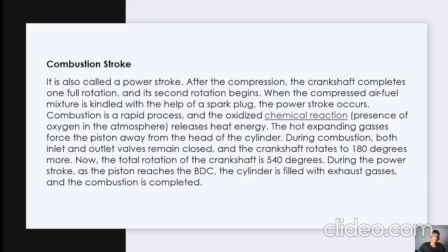Combustion stroke. It is also called the power stroke. After compression, the crankshaft completes one full rotation, and its second rotation begins. When the compressed air fuel mixture is ignited with the help of spark plug, the power stroke occurs. Combustion is rapidly processed, and the oxidized chemical reaction releases heat energy. The hot expanding gases force the piston away from the head of the cylinder. During combustion, the inlet and outlet valves remain closed and the crankshaft rotates 180 degrees more. Now the total rotation of crankshaft is 540 degrees.